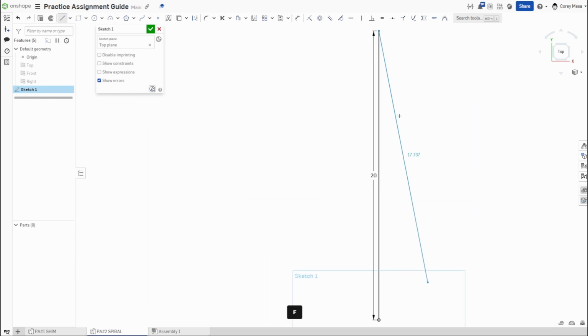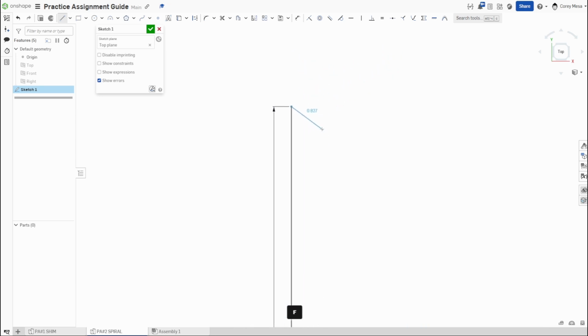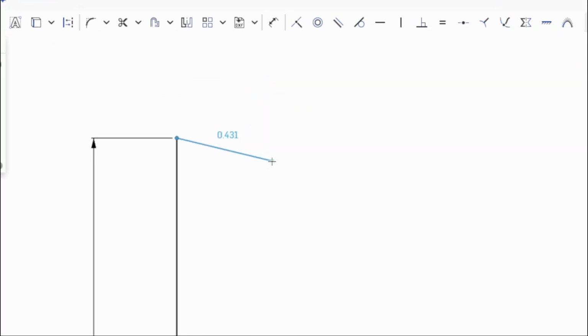So that's a cool tactic you can use if you're zoomed in too far, or the opposite, you're zoomed out way far. That'll help you make things good. So right now I need to go to the right, and I need to go 19. And if you look, I'm going to zoom in a little closer. As I get closer to that horizontal line, you'll see it'll snap, and that little horizontal constraint symbol pops up. Also, if I were to go vertical, you'll see that pops up.